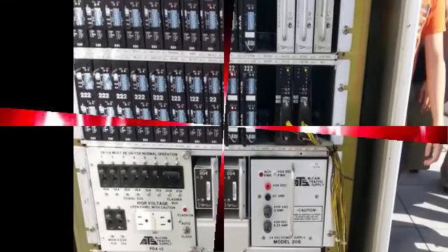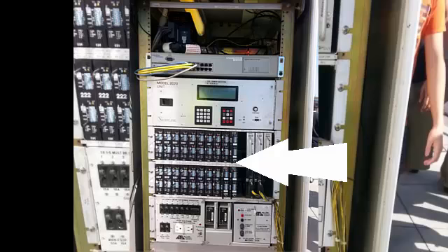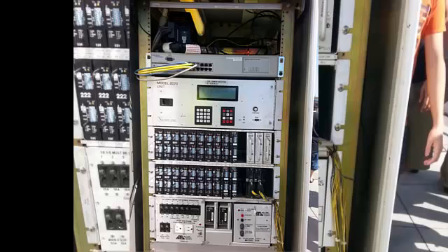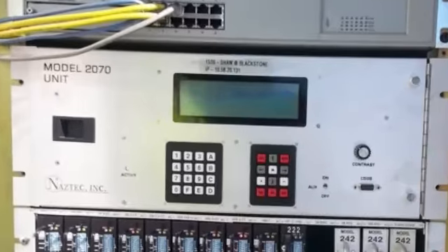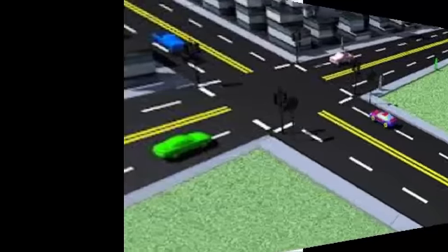Upon the detection of a malfunction, it immediately places the intersection into latched flashing operation, which basically means all lights flash red. The detector units identify vehicle actuations based on information sent to the unit by their associated field units, and they pass this information along to the controller for use in timing the intersection.